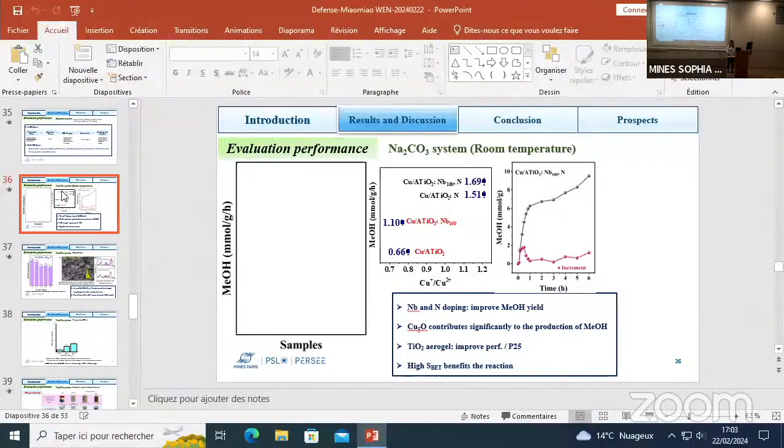You have used nitrogen adsorption, which is a very valuable method for sure. You have applied the BJH treatment, and we all know that for aerogels, but maybe not for yours, because calcinated, it is not really good to have the complete view of the porosity of the material, because you know the story, the densification when the meniscus is appearing and so on.